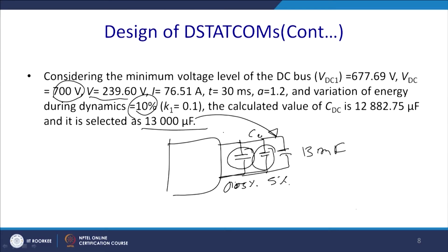That inductance is required to be suppressed. So, for this reason we have a switching, and these leads may actually act as an inductor at the switching frequency. So, to suppress those we have to parallelly connect this ceramic capacitor CE and the CT,